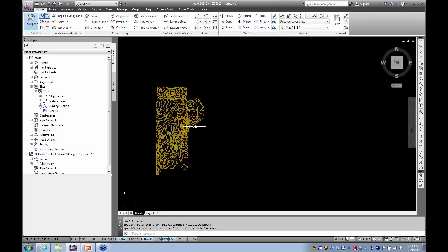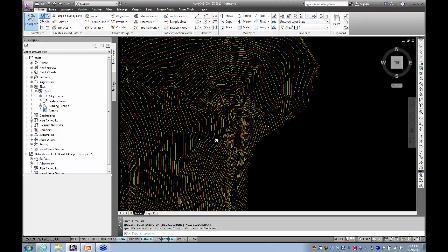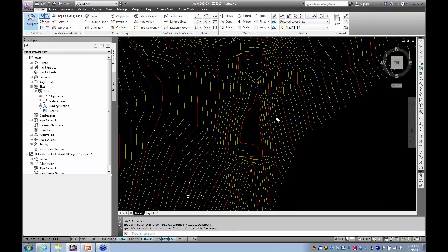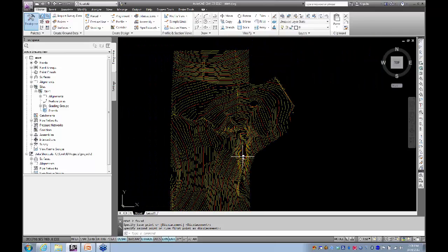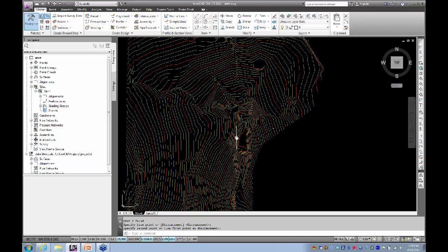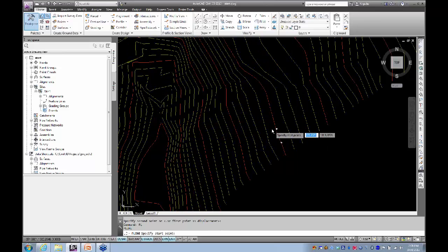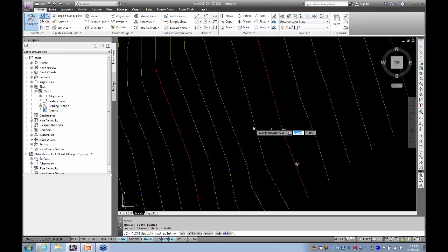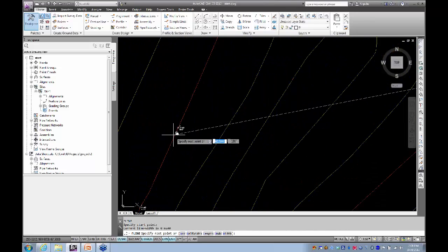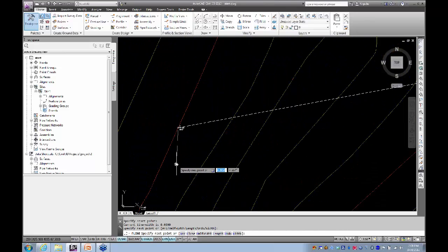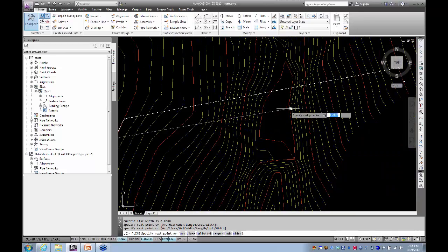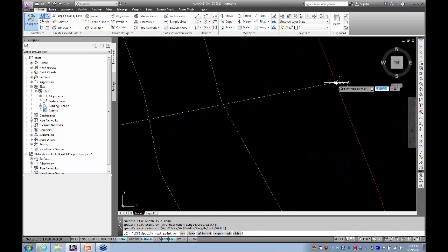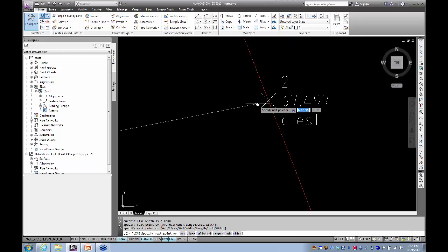Okay, so I've got my standard Civil 3D surface over here, and I've got a couple little points marked on it for the edge of where I want to put this little dam on the surface and make a pond up in the valley behind it to the north here. So let me start doing that. I'm just going to draw a polyline, straight out 2D polyline. It could be 3D if we wanted. Snap it to there, and go straight across to that point. I'm going to come down to my other marked point, and straight back to there. Should have that on node really.